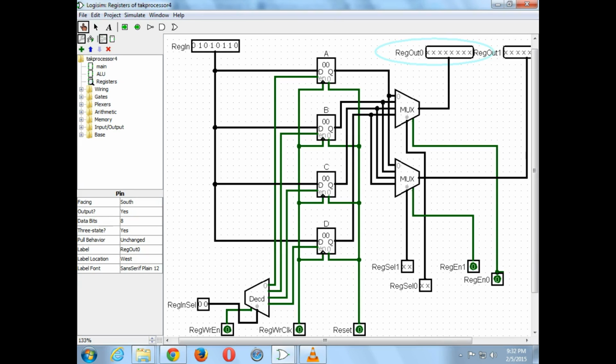Because there's no control to disable the ALU. The adder is always active. The subtractor is always active. It's just that whatever the input is may not be useful, and nobody pays attention to the output either. But then we can also disable the ALU output. Yes, you can disable the ALU output, but the input, it's the adder. You cannot disable the adder or the subtractor. Those things are always active. They're always interpreting whatever the input is and doing the calculation as the output.